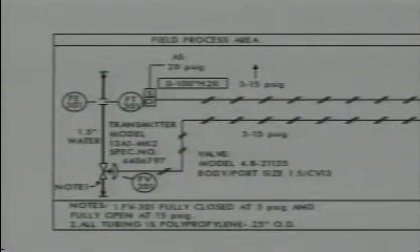Let's start again in the field process area and locate the primary element. The primary element here is also an orifice. The orifice is installed in a 1.5-inch pipe. The process material is water. At the transmitter, there are 2 connection ports labeled S and O. So the transmitter has a supply port and an output port. This transmitter has an air supply of 20 psig.